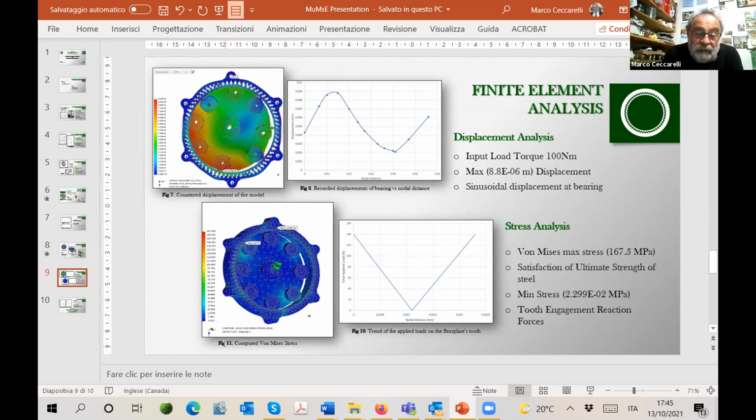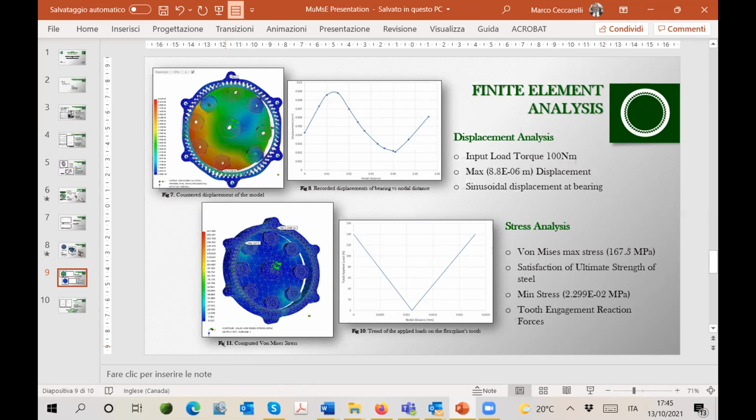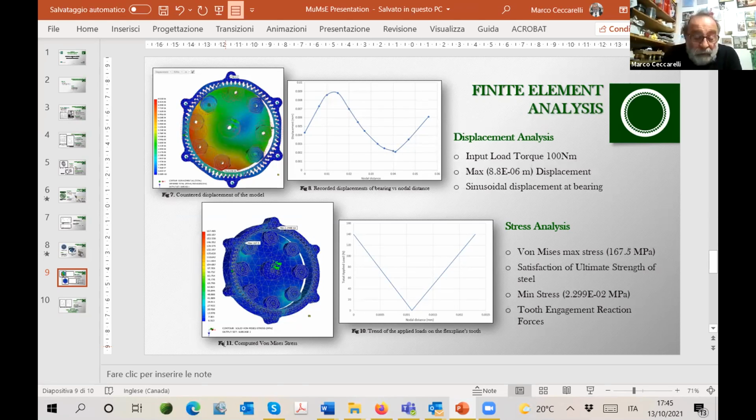Actually, as I mentioned, this is a student, but he simulated a reasonable friction at the contact of the teeth. That differs in this harmonic drive from the classical gear. Normally, classical gears do not have sliding at the contact point. Do you have sliding at the contact point here? Yes, because you have the flexible spline that is engaged during a motion.